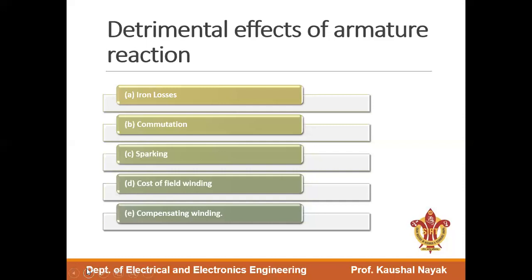In addition, a high degree of saturation in teeth forces the flux to stray into the core plates, covers, etc. This all leads to more eddy current and hysteresis loss. Roughly, the iron loss at full load is taken to be 1.5 times its value at no load.